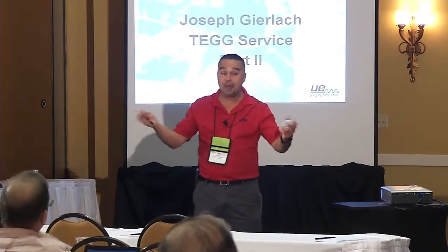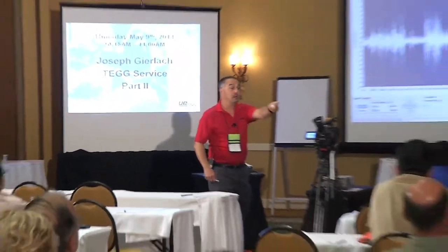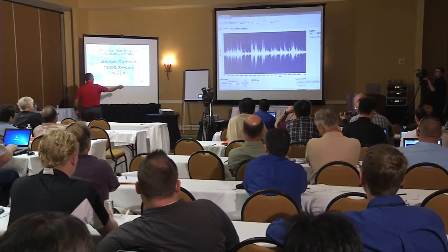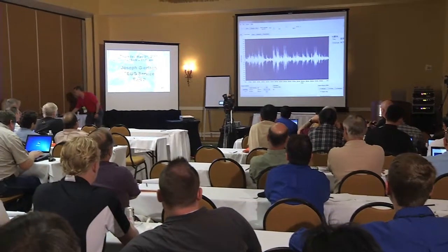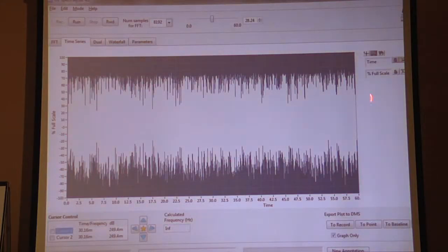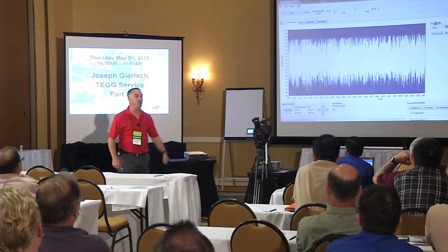So, anybody have any questions? Yes, sir. Why would you eliminate arcing from this one? Good question. Because if I look at the entire 60-second recording here by double-clicking the stop button, is there any point in that 60-second recording where it goes totally silent? Not one. That rules out arcing.